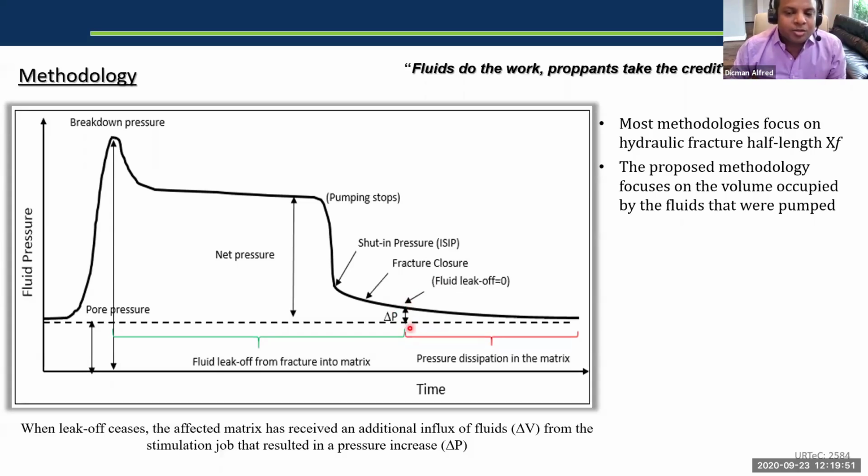No, you can't. So it is also important to note, even after the fluid leak-off stops from the fractures into the matrix, the pressure is still dissipating into the matrix. The pressure continues to leak off. And this is what people typically do when they want to establish a reservoir permeability and pore pressures. They analyze this part of the curve, your pseudo-radial flow. We don't have time for all that. But I want to know at what point I've completely expelled all the fluids into the matrix.